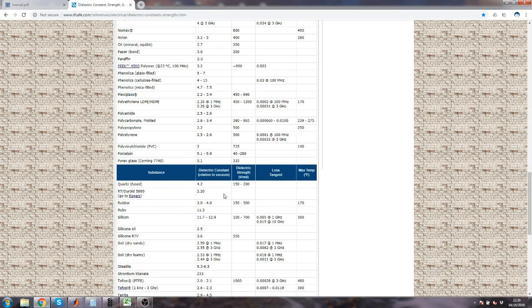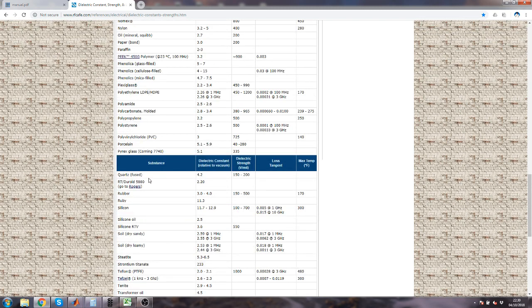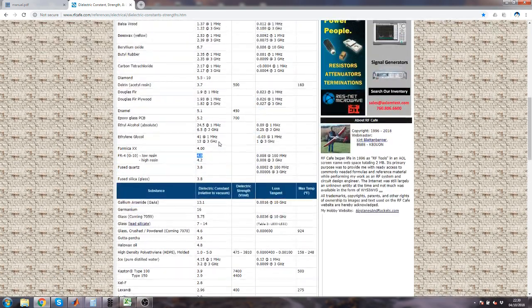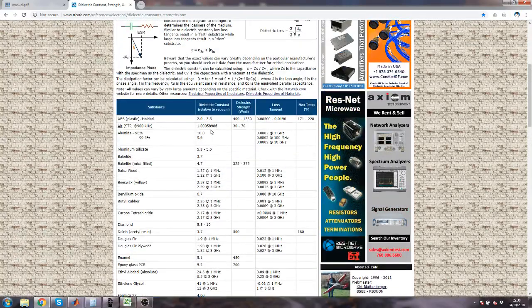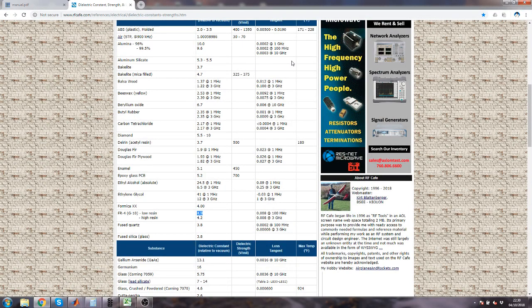manufacturer of lots of high frequency boards that are made of a variety of other things. And you can see if you look at the Rogers, this is just one particular one. It's got half the dielectric constant of the FR4. Really, the ER is not terribly important. That's the real part, because the epsilon actually has real and imaginary parts. The bit that deals with the loss is really the relative size of the two of them. But we needn't get into that now, because this is not really an RF thing that we're looking at. Anyway, I picked this because I can.